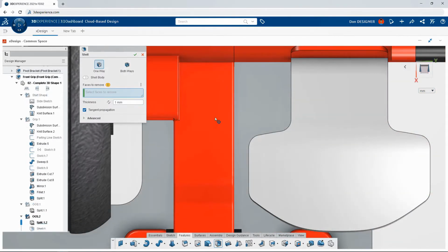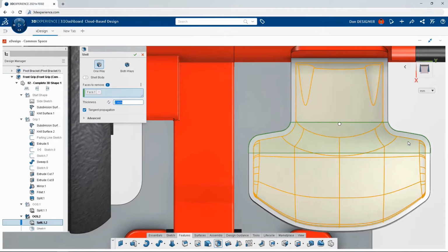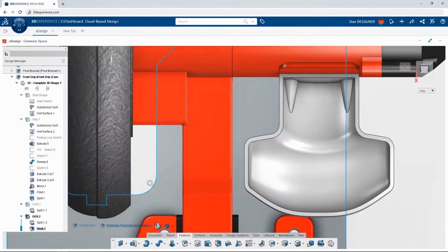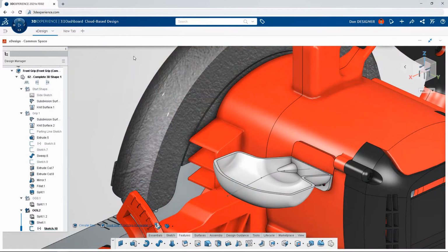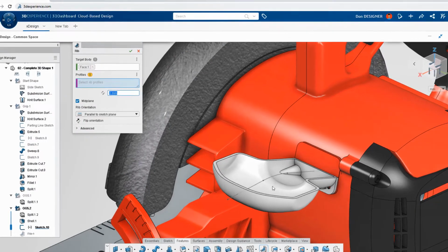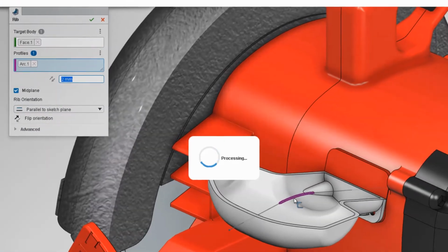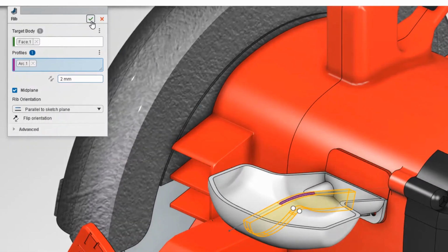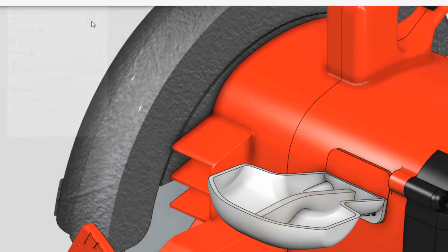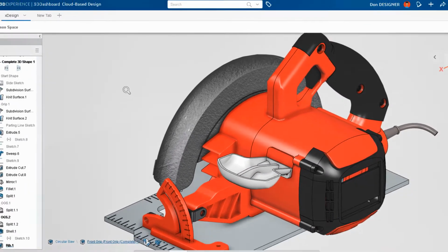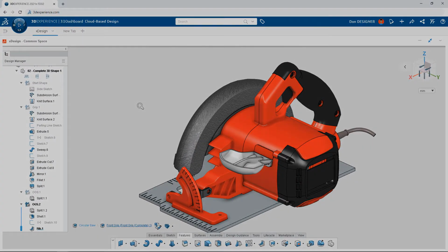To lighten the design and prepare it for moulding, Don adds a 2mm shell feature. To reinforce the hollow design, he can sketch a profile for a rib. Even without perfectly trimming or extending the sketch entities, the rib feature will project the geometry to fill the internal volume of the component. If necessary, draft could be added at the neutral plane or where it intersects the inside walls of the part.